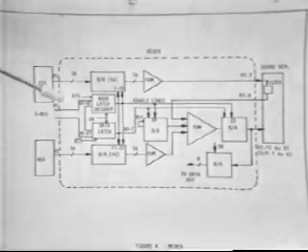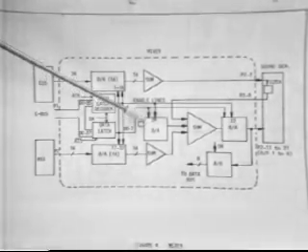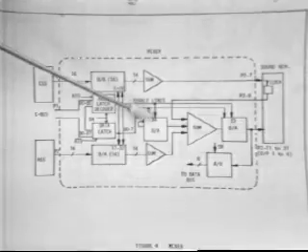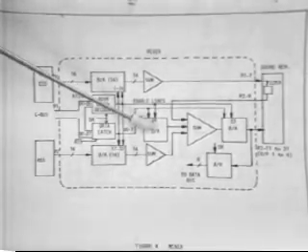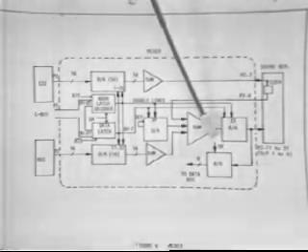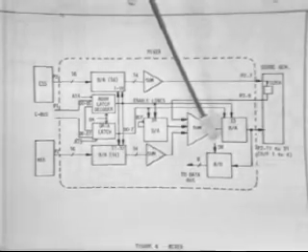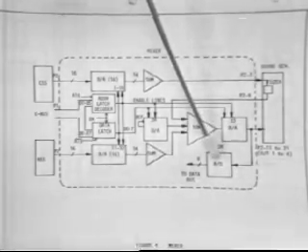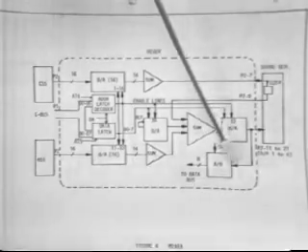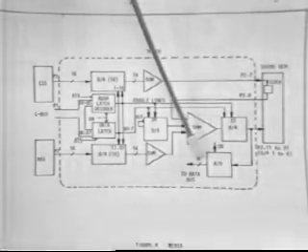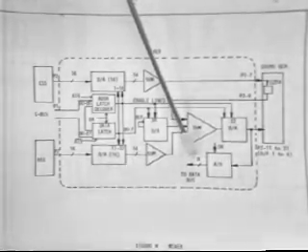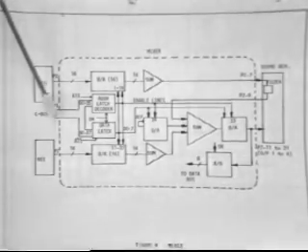When we want to test this particular circuit, at the same time as output 34 is enabled, we will have a DC voltage present at the A to D, so that our DC voltage is reconverted back to an 8-bit word sent back to the C-bus.